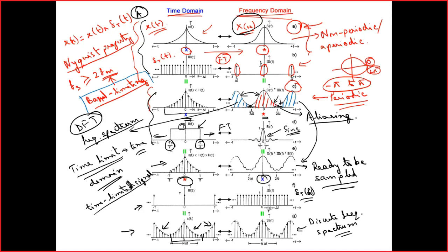Okay, so this is the essence of the discrete Fourier transform. In the discrete Fourier transform, both the time domain signal and the frequency domain signal are discrete in nature, and due to this reason, both the forward transform and the backward transform can be processed in a computer, which was not possible in the discrete time Fourier transform and inverse discrete time Fourier transform pairs. The reverse was not possible over there.